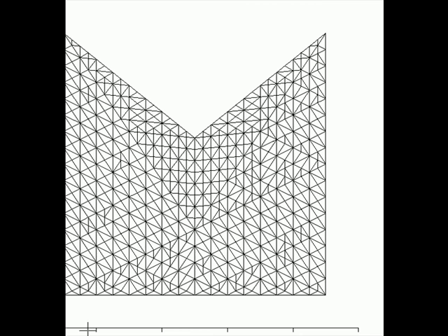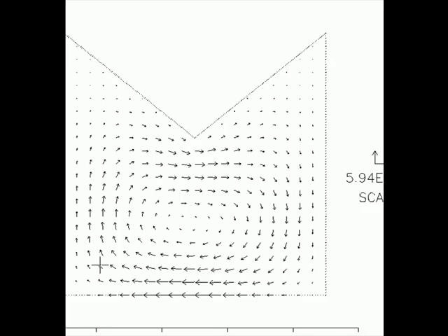And there's the final triangulation of 1,000 triangles. And there's the fluid field, and remember on these 4 sides, u and v are both 0. See, there's no free flow here. It's like a sticky boundary where u and v are both 0. Down here you have free flow. That means the fluid can slide along the boundary, but it can't cross the boundary. So everything looks like it ought to be, and it's swirling because of that body force, basically a swirling force.